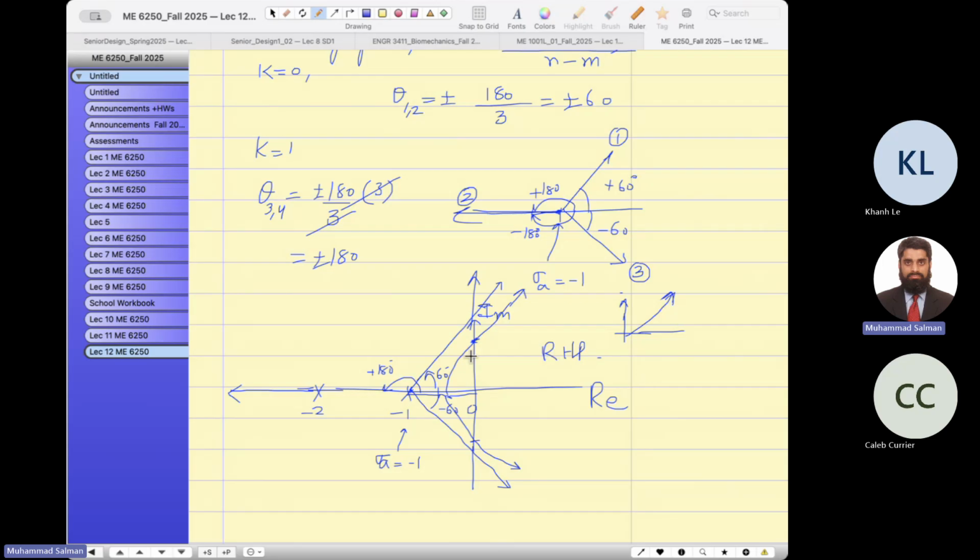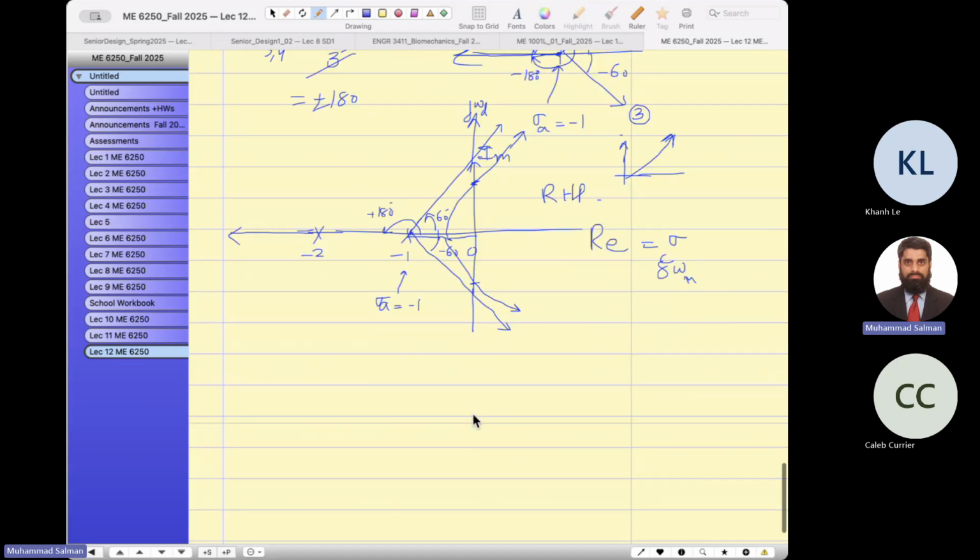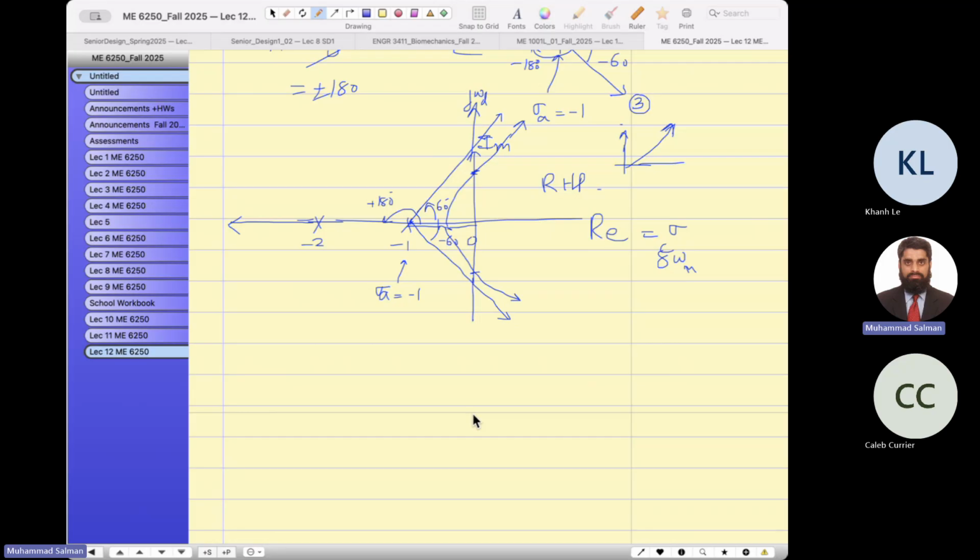So we don't want our poles to pass this imaginary line, the j omega axis, and this real axis is also known as sigma or zeta omega; these are abbreviations. Whenever a pole passes through the imaginary line, the system becomes unstable. You see my point? The response becomes exponentially increasing. It does not come back to the mean position. We want to keep our poles in the left half plane. So let me show you. The left half plane is our desired plane for stability of our system.